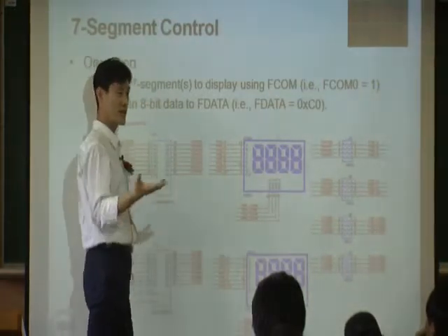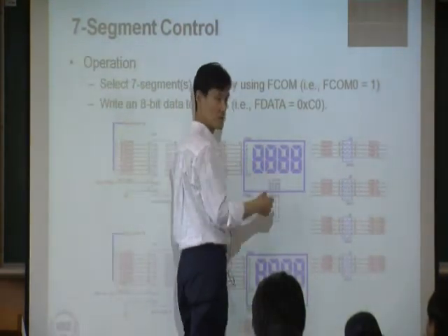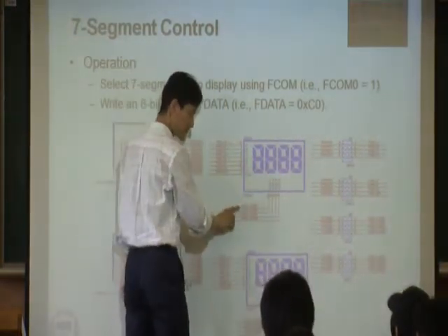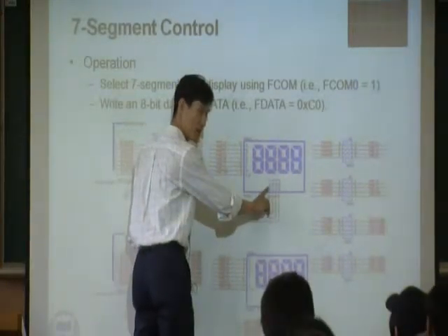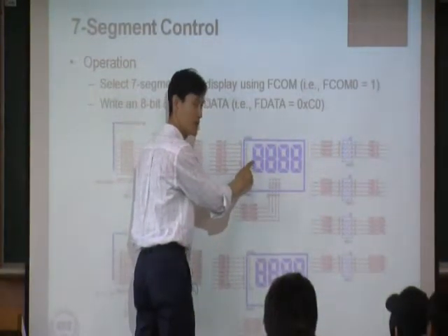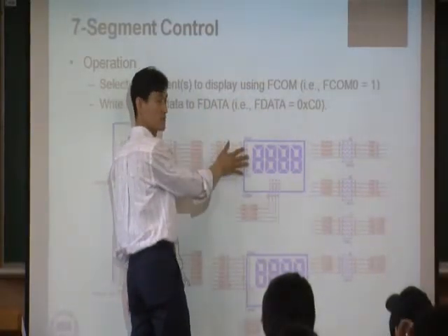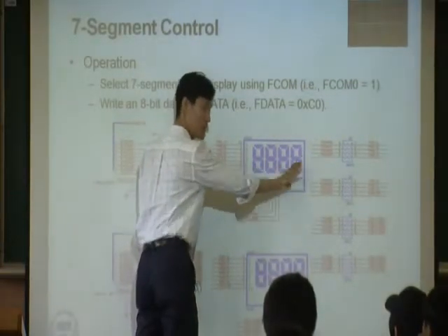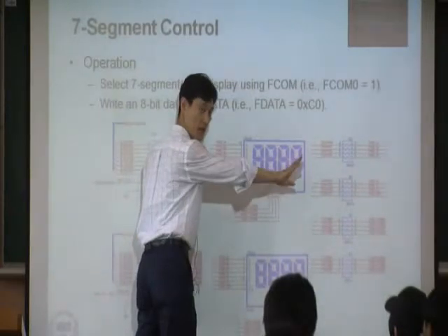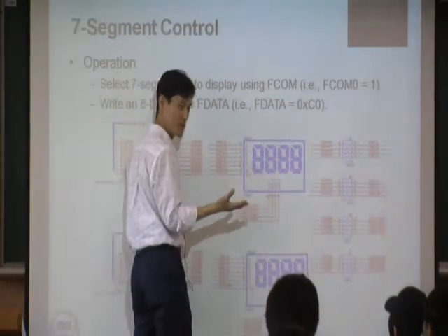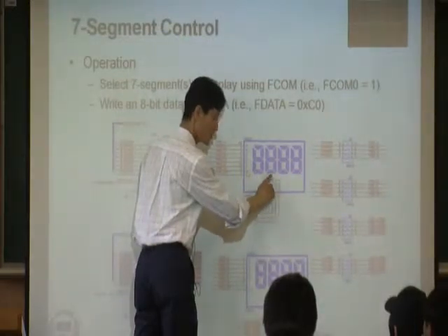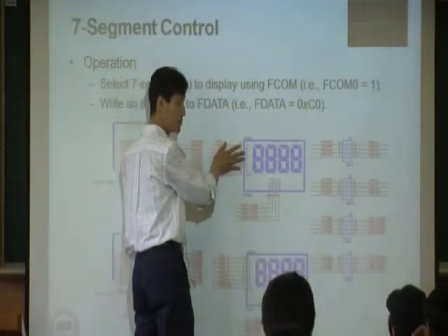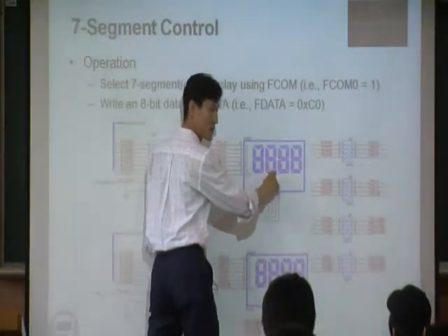Now what do you want to do? Let's say you want to display 2315. In that case, you turn on the first bit. This 7 segment is now enabled, and you send the 2. Only this one will show 2. All the others will be disabled, so they're black. And right after that, you turn on the second pin. So you turn on the second 7 segment, and then transmit 3. Then, of course, only the second one will show you 3.